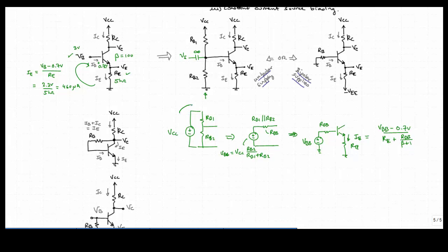Now we can also consider a bipolar version of this same biasing, or the same amplifier. And notice that in the one we just looked at, we were grounded, so we were at 0 volts and we were at VCC. Now we're going to have VCC and we have a negative voltage, that's minus VEE. So what we'll do is we can just tie the base to ground through a base resistor.